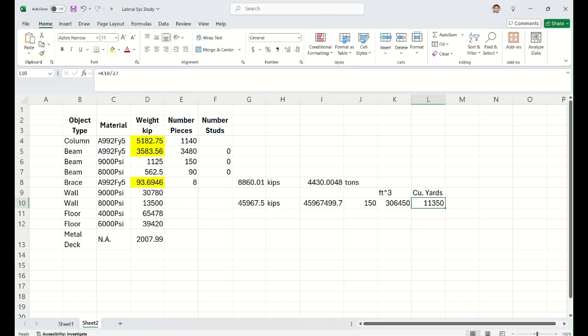Right? So I think what you summarize is both steel tonnage and concrete volume. Structurally, for our reference, we sometimes differentiate the tonnage of each column divided by our reference total floor area, right? Or let's say each floor beam divided by your total floor area gives us the general pounds per square foot, right? Typically beam framing is less than 10 psf.